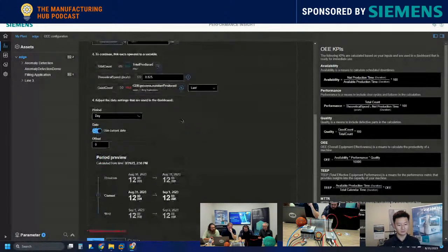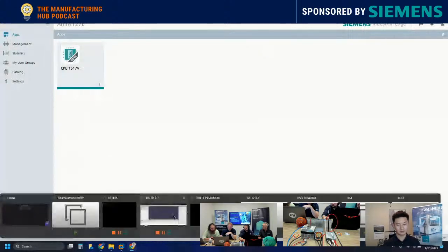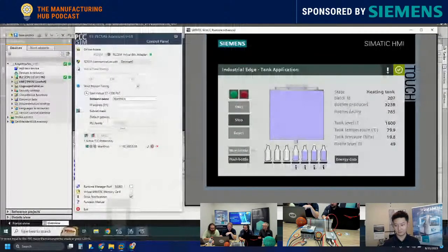I guess we have a question from Nan. He's asking, in this case, does the OE data come from the virtual PLC, or is it coming in from PLC Sim Advanced? Right now in this application, I haven't loaded anything into the virtual PLC. So the virtual PLC is sitting here, but it's a blank, empty PLC right now. Everything that we're looking at right now is coming in from this PLC Sim Advanced. And we'll load it into the virtual PLC, Adam? Well, that's what the plan is. Good. So the answer to Nan's question is we're getting there.